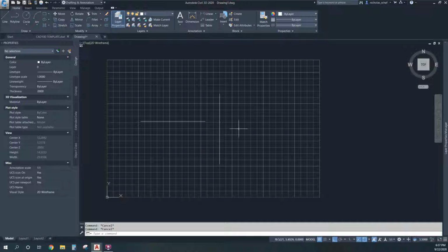They are perpendicular to each other. So when you do the trim command, and if you select all, you could trim off that, you could trim off this. There's no way to trim that part, but the other helpful thing is if you hit shift while you are in the trim command and all of your objects are selected, you can actually extend, and we will talk about extend here momentarily.